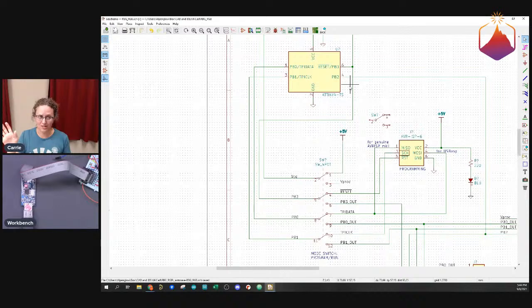So that one generally is dedicated. That leaves us 3 pins, and we need 2 of those for programming, so obviously they're going to be multi-purpose. So I hooked them up to a switch so that we can switch those lines to go to the programmer, or switch them to go to the rest of the circuit. While we're programming, they won't be connected to the rest of the circuit.